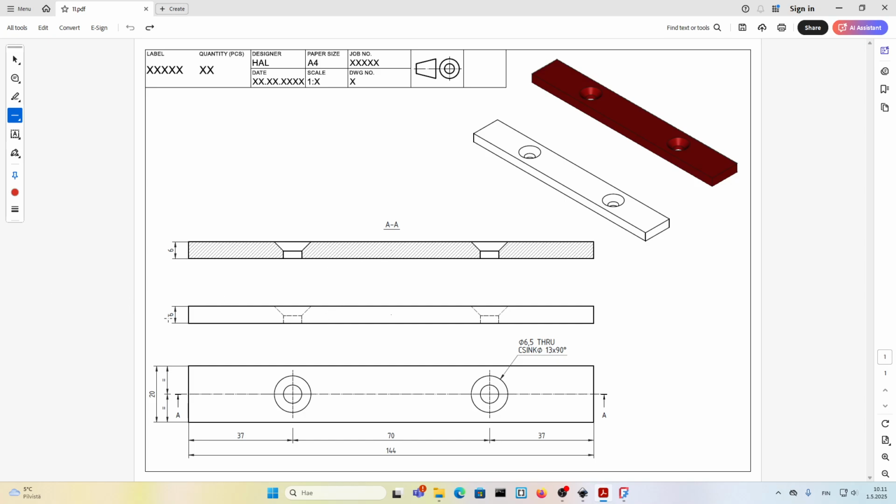In here, you can see we have a plate, which is 6 millimeters. Now, when you have a dimension 6 or 9, always to distinguish them from each other, add behind the 6 or behind the 9 a dot. Now I don't have the dot, I forgot it, but always add a small dot in here to separate the 6 from the 9 to avoid mistakes.